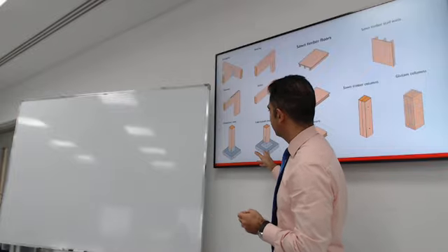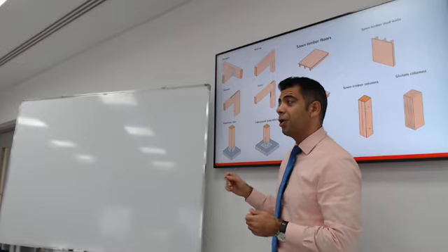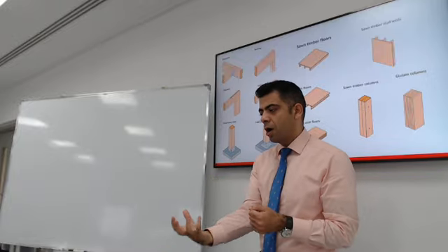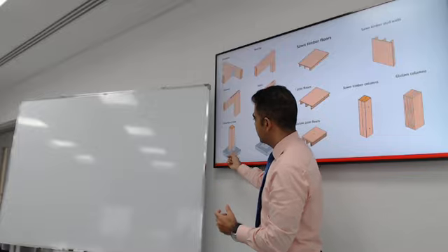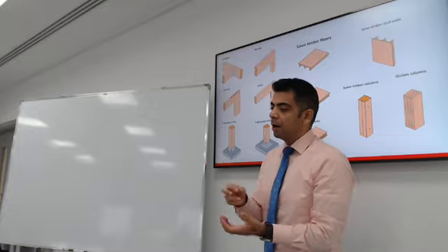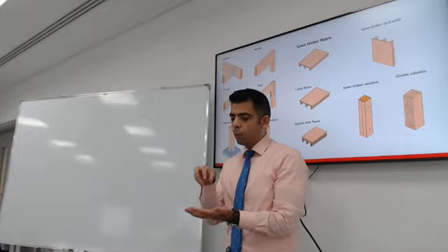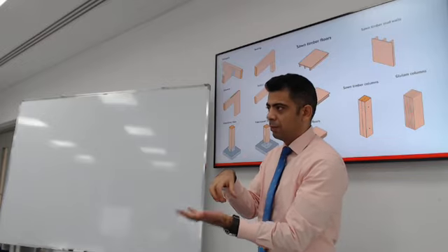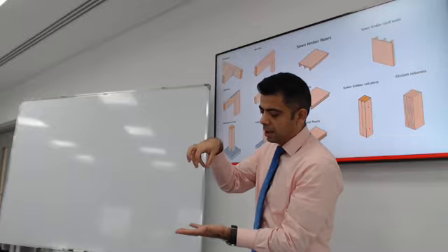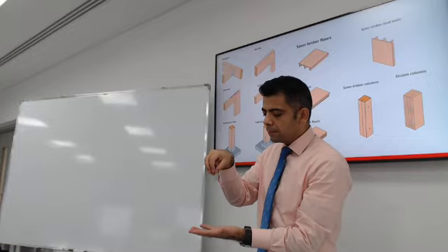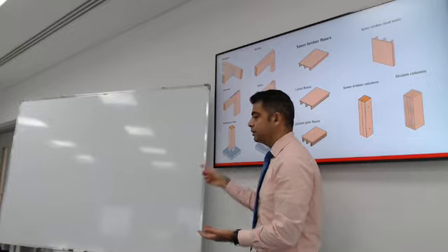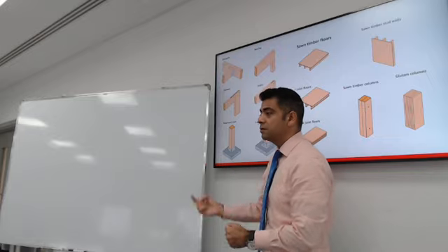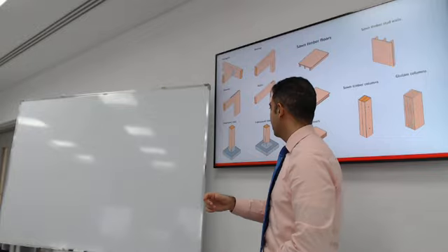What would be a good material for foundations? Concrete. Concrete is very durable. You can use concrete. So you can have a connection between concrete and wood. You can use these accessories. Some of them are called wet cast, where you put this in when the concrete is wet. So before the concrete hardens, you can install this part in the location where you want it, so it's nice and ready to receive the column.